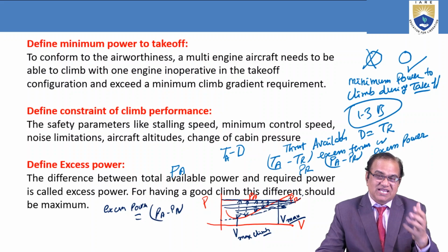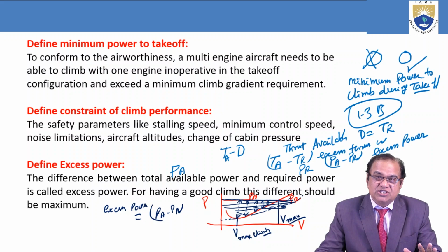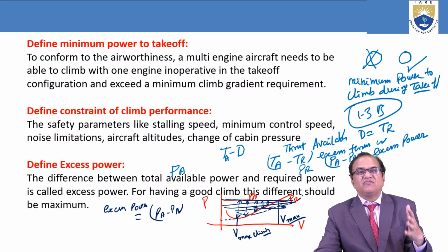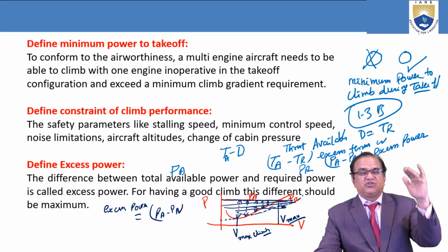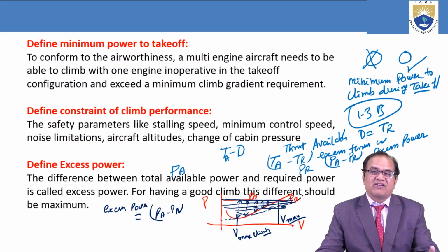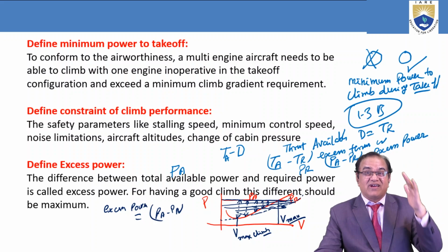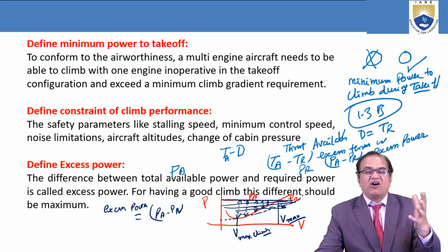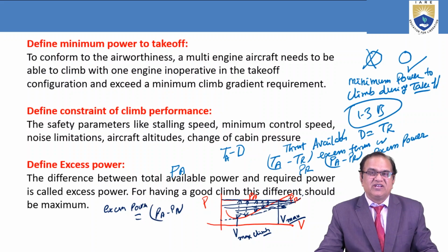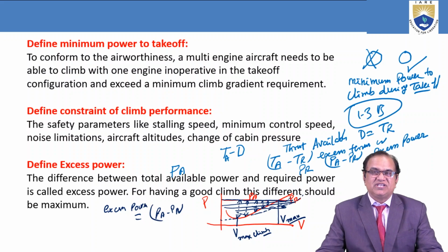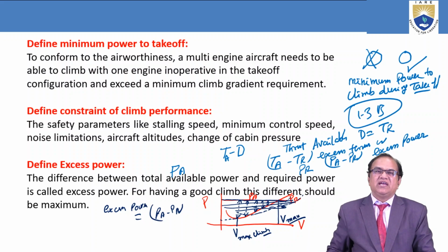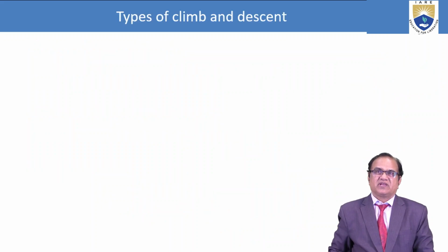So during selection of the aircraft, we have to make sure that whatever condition we have been given, our aircraft should be able to meet that altitude. A higher altitude aircraft is very safe, because if another aircraft cannot fly up to that altitude, it cannot dogfight with that aircraft. So that is the intention for the service ceiling. It is a very important parameter. The absolute ceiling is also a very important parameter for any aircraft performance.